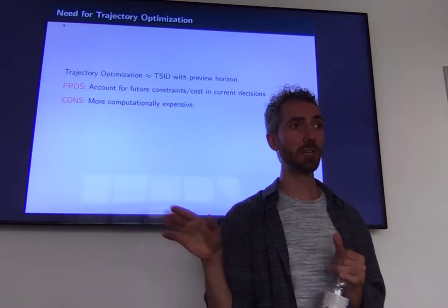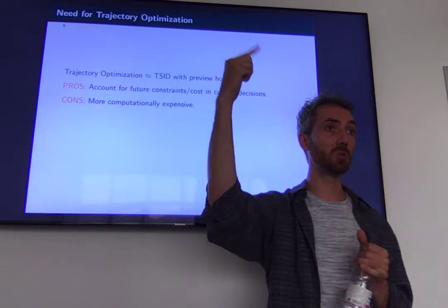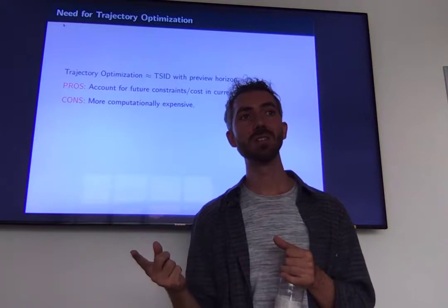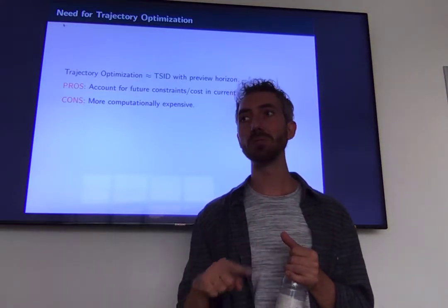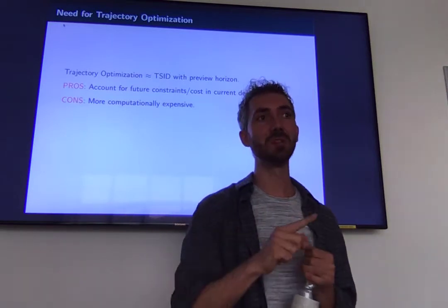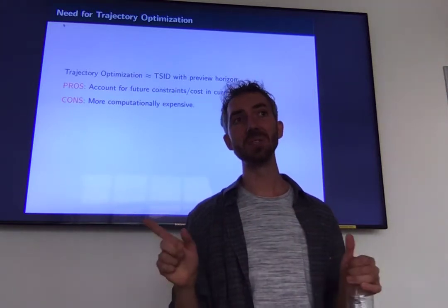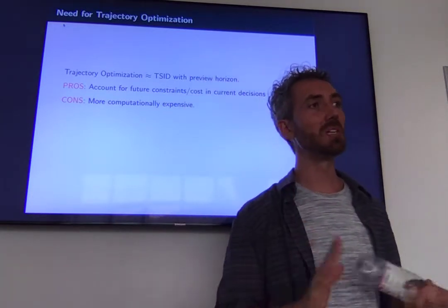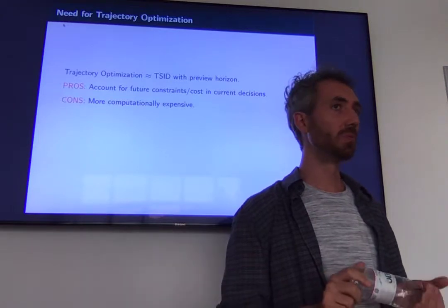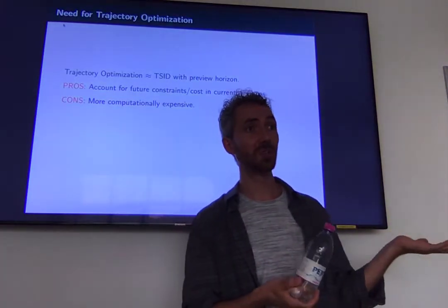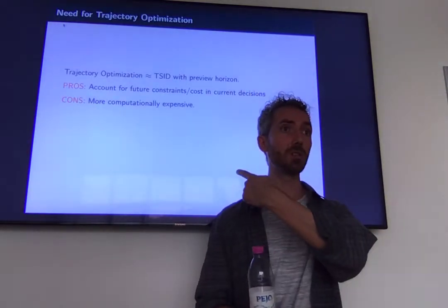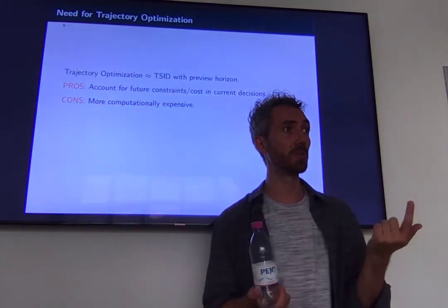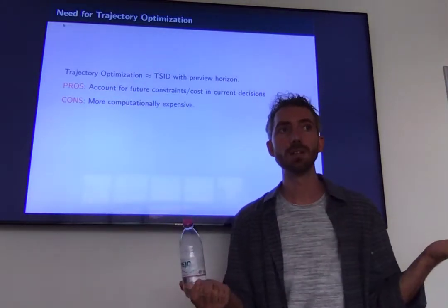That's for the control. Then you typically have also the position and the velocity, so you multiply times 3, you get 180,000 variables. You cannot solve an optimization problem with 180,000 variables in 1 millisecond, not even in 10 milliseconds or in 100 milliseconds. I mean, it's going to take probably minutes to solve. So that's why we used reactive control in control loops, because trajectory optimization is too slow for reactive control loops. Otherwise, we would use it if it was sufficiently fast, because it's better.